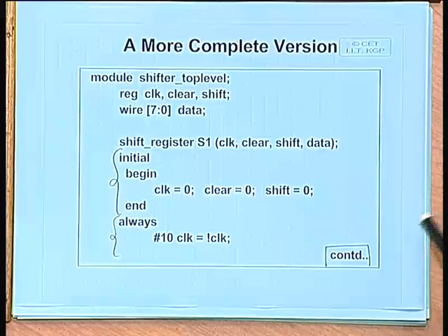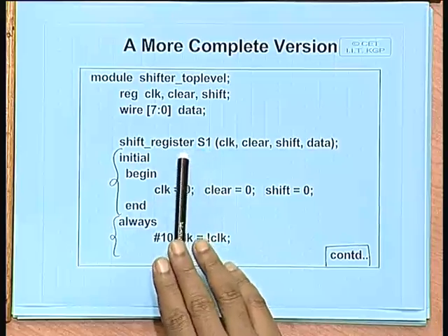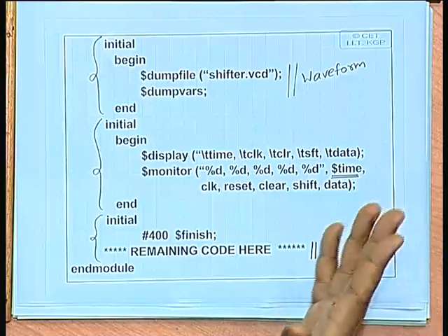Okay, your question is how are you integrating this with the test bench. So, that I have not yet mentioned. Let me now look at a complete example that will show exactly how you will normally use it. Whatever I have shown till now is just for the sake of illustration. This is your main module, and these are the functions you write as test bench, you integrate them. But normally, as I have shown in an earlier example, you have a module under test and a test bench, and you instantiate both of them inside a top level module. That is how you normally do it. Now, I will give an example like that.